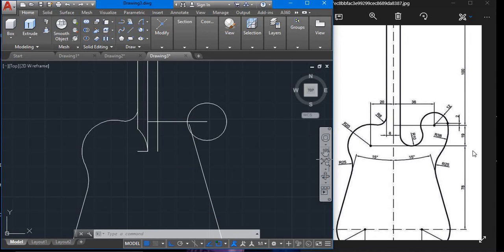And the next one we are going to draw is this particular arc here, and I will be getting that from the circle. But before then, I will draw a reference line from the end of 19, the middle line here, which is 19. So I'll type my L, enter. I'll take a line, dimensionless all through here, then I'll left click and escape.